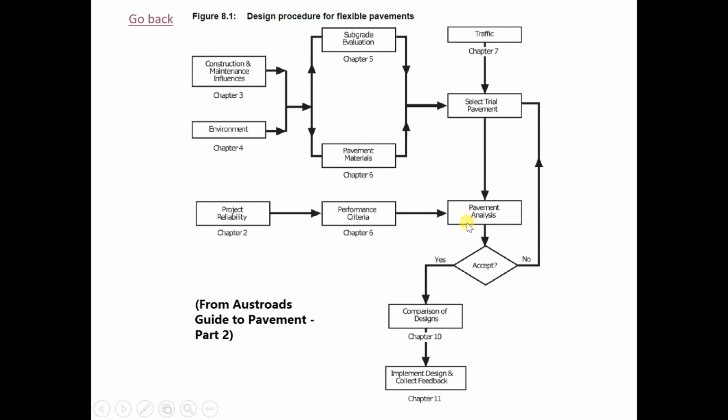Like in structural analysis, we have a safety factor for the dead load, a safety factor for the live load, and for the wind load or earthquake loading. This also depends on how reliable you want it to be. So you can input some value, some constant, that can be added to the design.